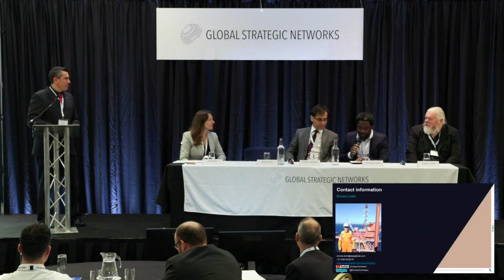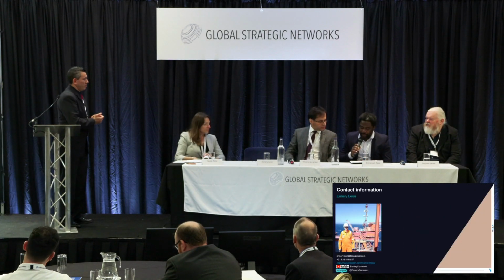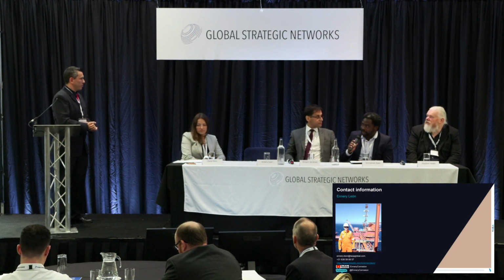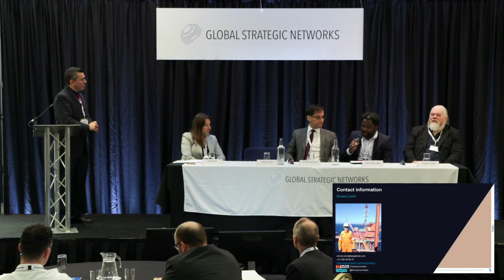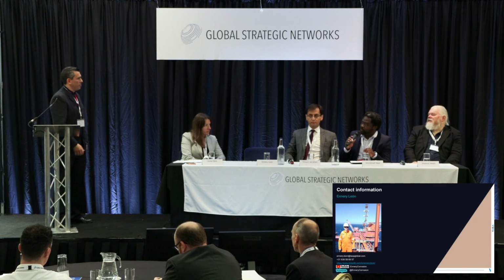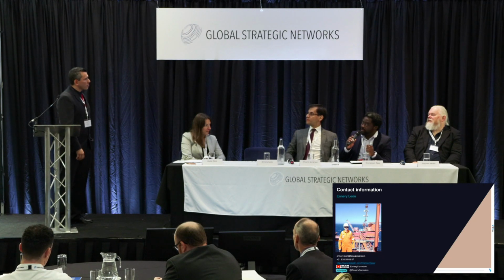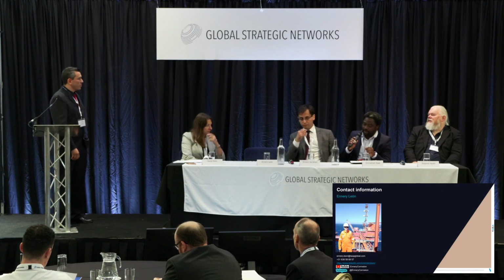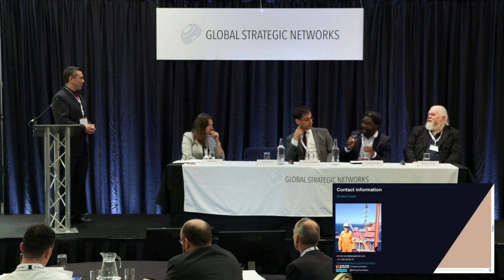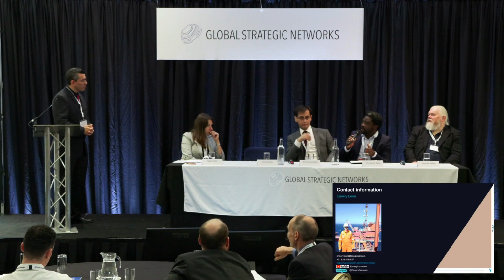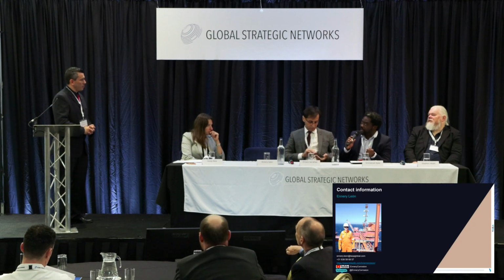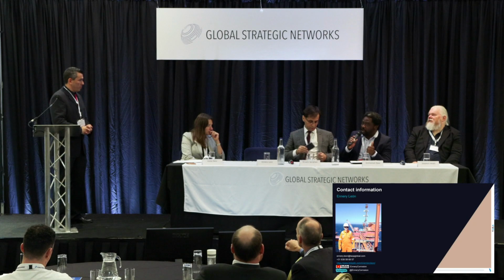Just 3 quick comments that I've got here. The first one is around the frequency of removing the probes, and I think from an operator's point of view, I would rather have a long-term probe that I can retrieve once a year than one I'm going to retrieve every 3 months, because some of those probes were installed such that you cannot retrieve them online. It's the best advice to make sure that if you have ER probes installed, you can retrieve them without shutting down production.